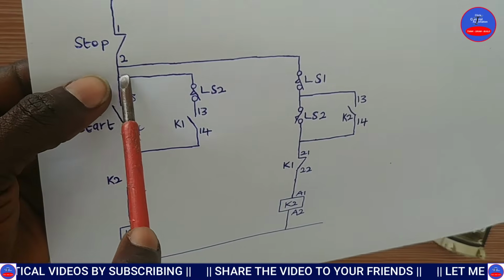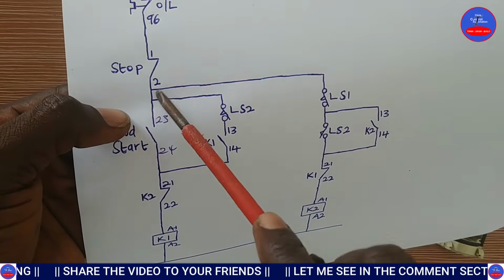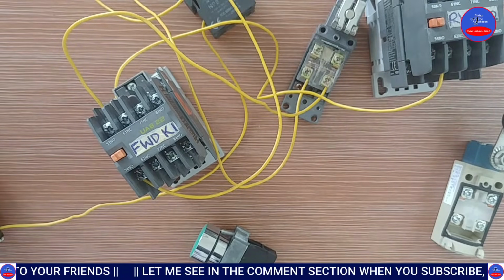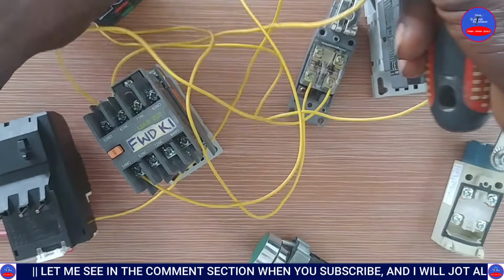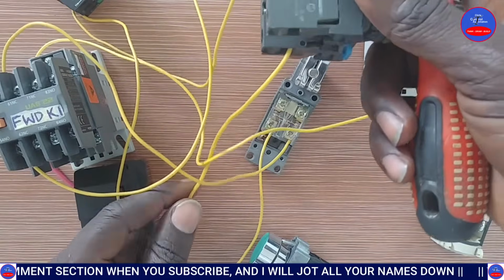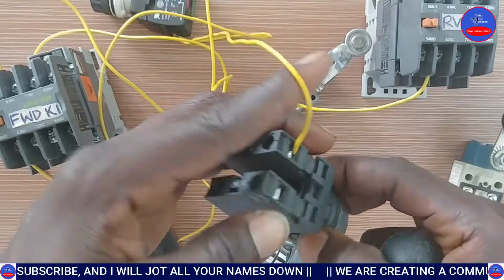We are going to continue from the same place. You can tap from the start push button or the down of the stop push button. So let's tap it from the down of the stop push button, to one side of the close contact on the limit switch 1. So this is our stop push button. This is from the overload. So the down, this side, the same thing. That's 1, 2.